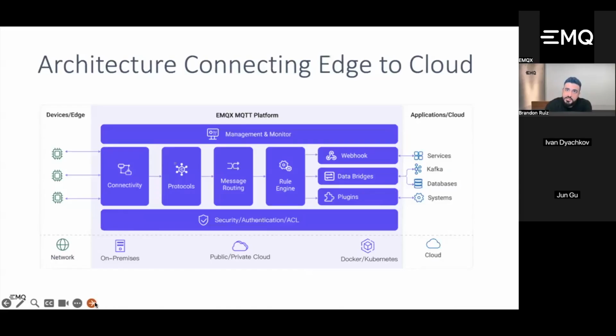This solution that is deployed amongst your devices in the field is going to ingest the different protocols and communications from all of your devices. Neuron EX today has support for just north of 100 different industrial protocols. It will take in all of those different communication standards, unify them and convert them into MQTT, and pass them to the broker. From there you can run it through a rules engine, where you can program more logic on where you want your information to go and in what form factor. And then from there, you're able to run it through streaming services like Kafka, Confluent.